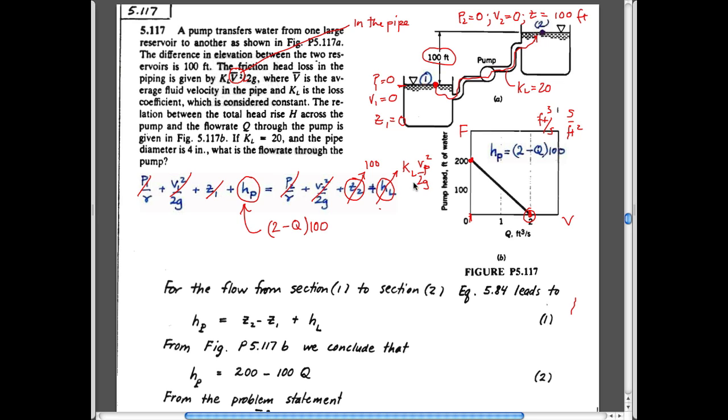We have a velocity here. And so we can write the velocity at point P. Do we know the velocity in terms of the cross-sectional area of the pipe? Do you know the pipe diameter? Oh, yes, yes, yes. So what is it going to be? Velocity at point P is going to be equal to the volumetric flow rate divided by the area of the pipe. Area of the pipe is going to be pi d squared upon 4.